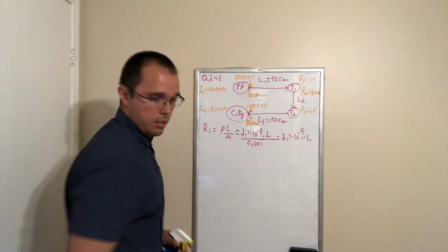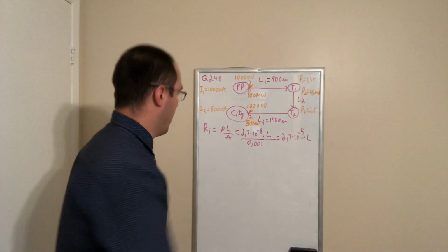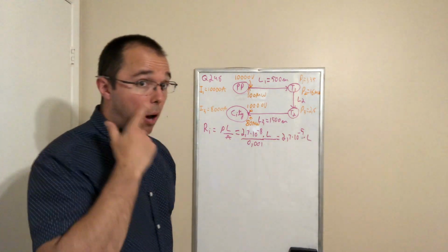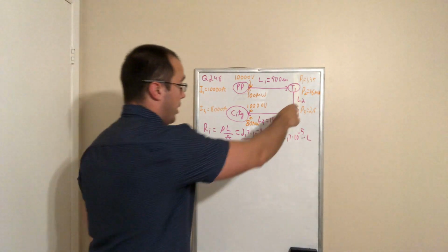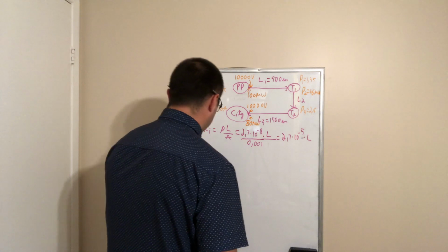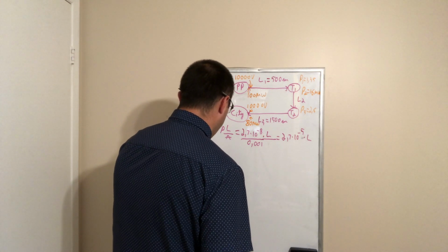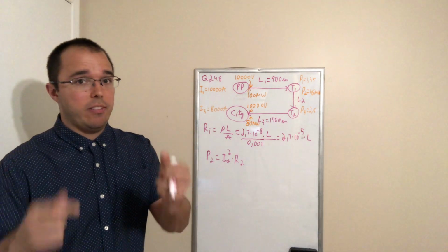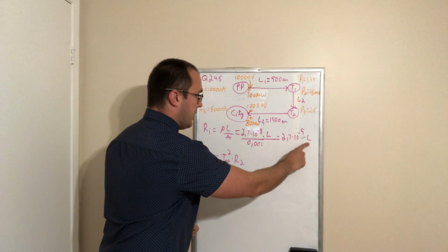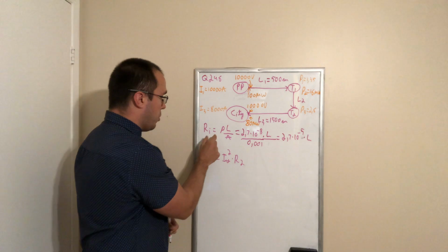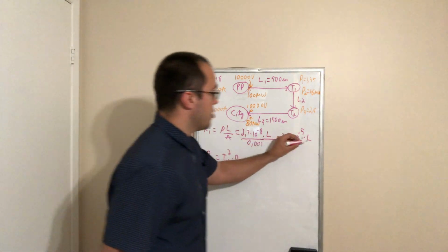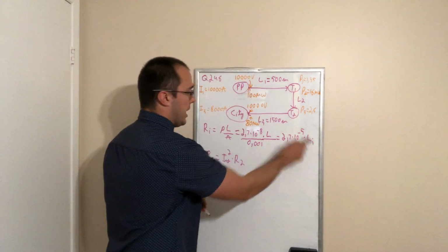All right, brand new. Okay, so now we know the power on the second power line over here. So we know that P2 is equal to I2 squared multiplied by R2. We want to find the length, L2. Well, using the resistance over here, once we find R2, we can use that term to find the length. Oh, by the way, there's an i over here because it depends on which length we're considering.